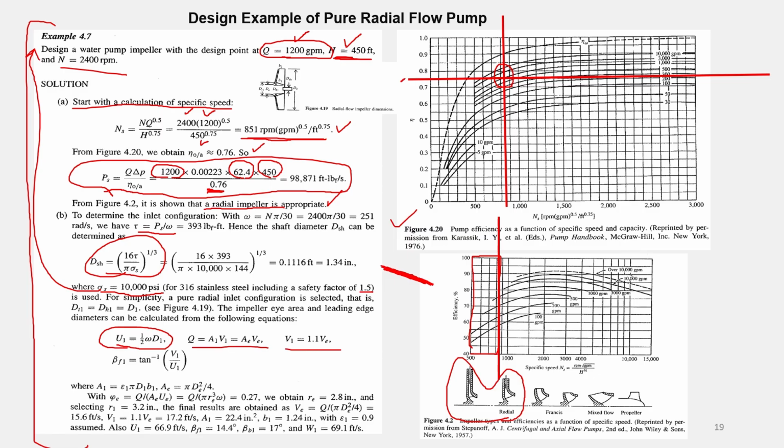And then I have told you that in order to avoid boundary layer separation of the flow, we make the flow velocity at the leading edge a little bit greater than the absolute flow velocity at the eye of the impeller, and it's taken as 10% more than the eye absolute velocity. And the flow area is pi d1 b1 or 2 pi r1 b1, but it's multiplied by a contraction factor here to account for the losses that occur in the intersection.